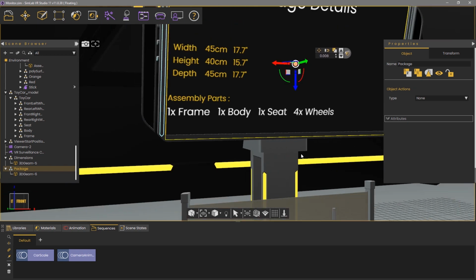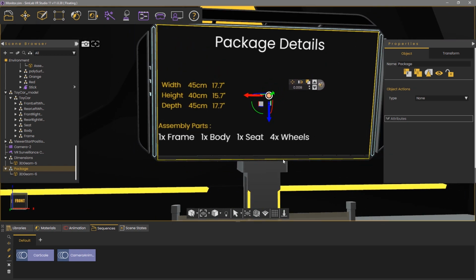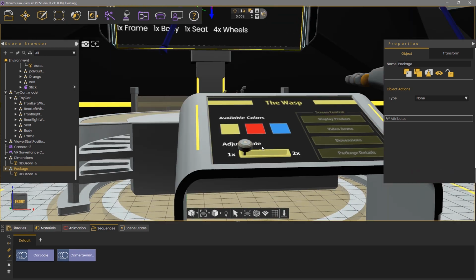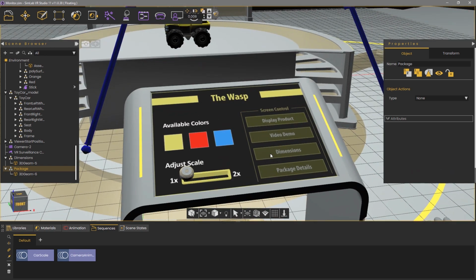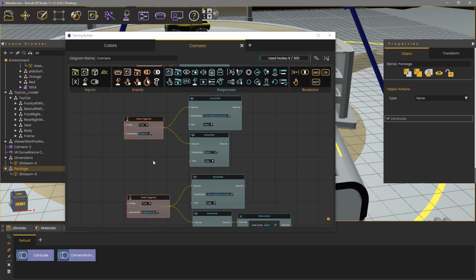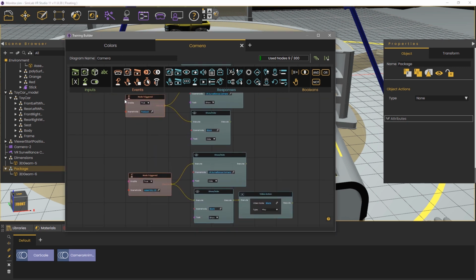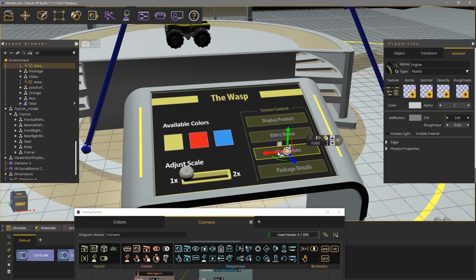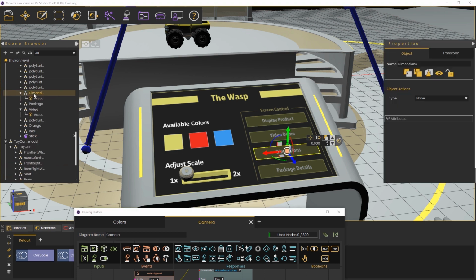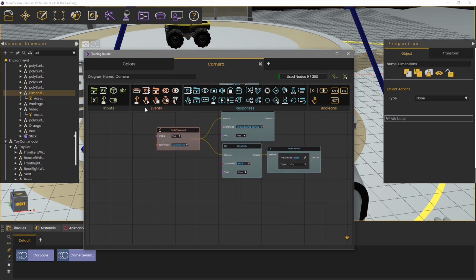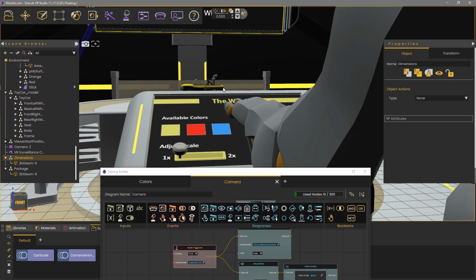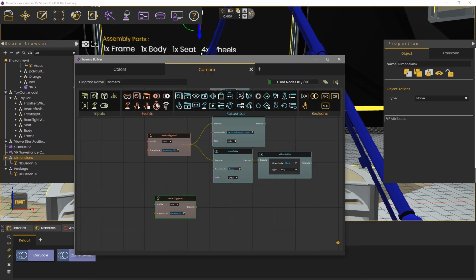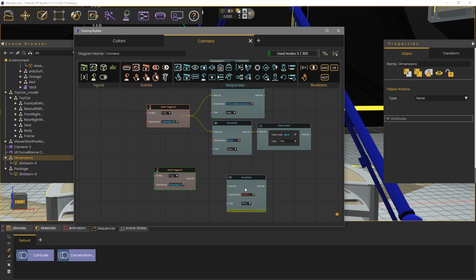Now that both planes are set to emitters and their placement is fine, what is left is to make the buttons that trigger them functional. Open the Training Builder. Then select the Dimensions button and add a node triggered event and attach the button to it. From the object tree, select the Dimensions plane, then add a Show and Hide response and attach it to it, then attach the response to the event.